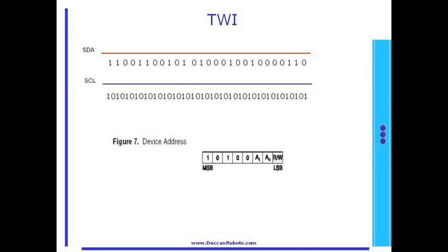The master microcontroller sends the address byte over the SDA line before sending any real data to the target device. Each device like 24C256 or DS1307 has a built-in address. The device address value is mentioned in the individual datasheets. One such address is shown on your screen.